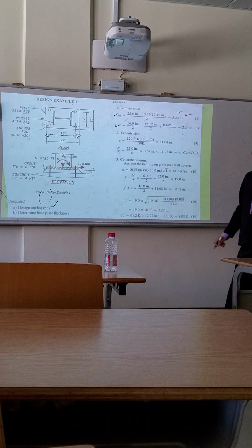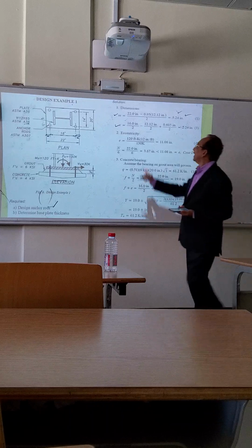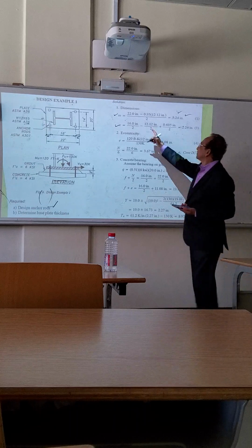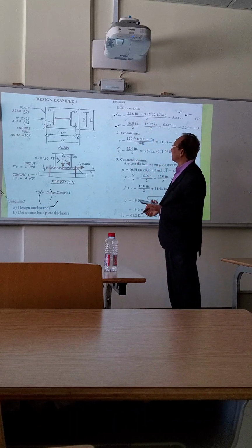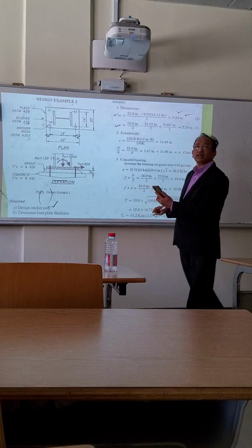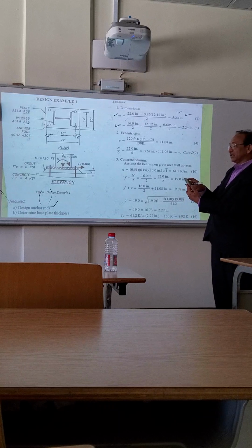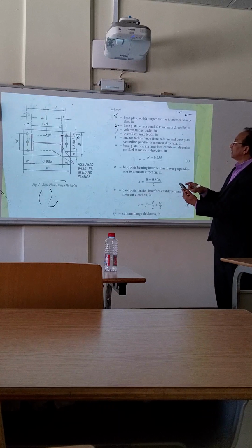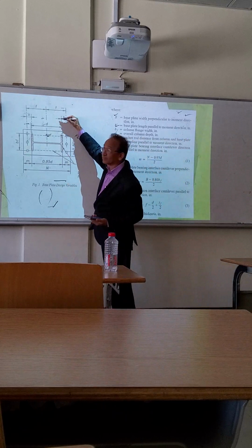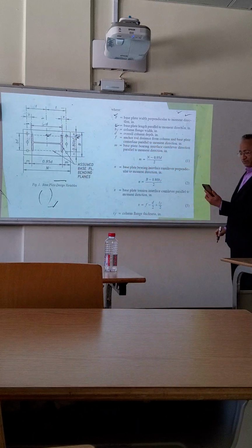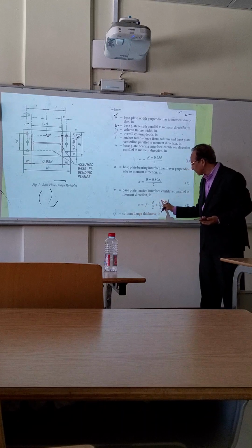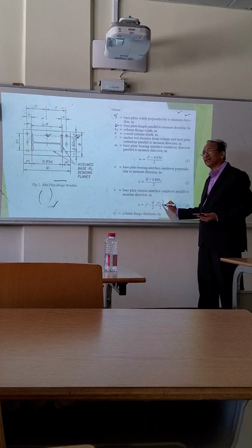So you get M. Similarly, X you can calculate by that formula which you have already seen. So based on that we find the value of X in the previous one. If you remember that figure. How to get the X? X, again go back to that initial figure. See this X. This is your X, this distance from the figure on your slide number 12. So X is calculated based on this F minus D by 2 plus TF by 2. TF is thickness of the flange.